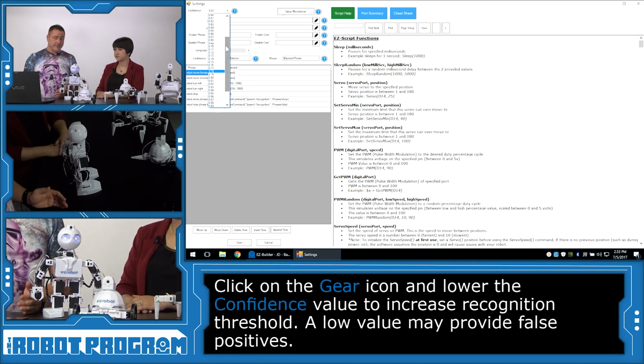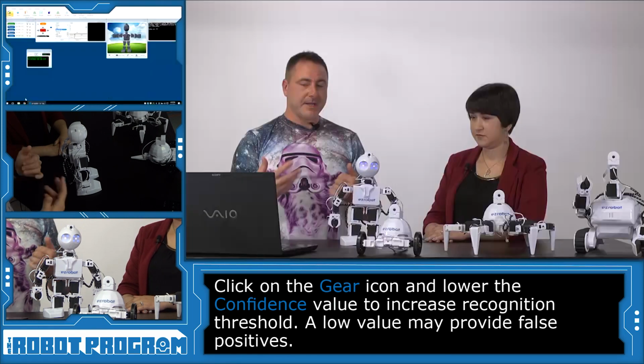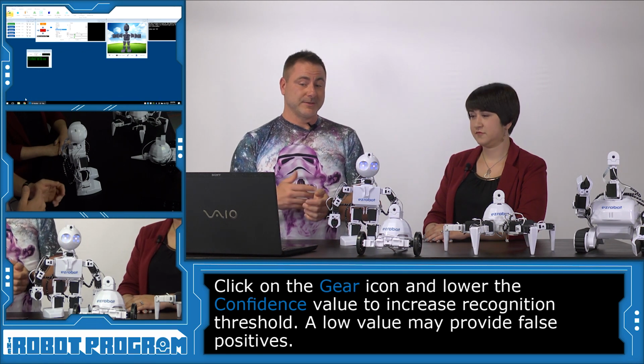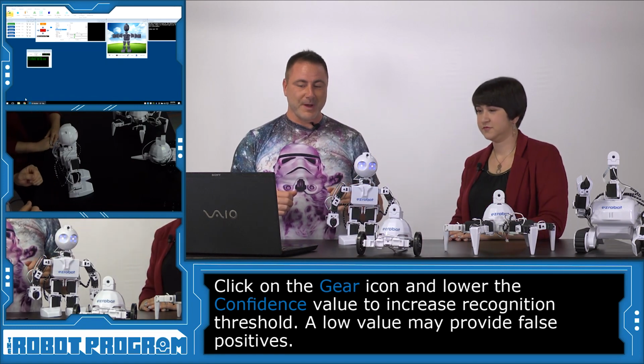That means we're probably going to want to bring this down to around 0.60. Now, it will work, but if I'm just talking out loud like I'm talking right now, it may think I'm saying something and pick up some commands. So right now it seems to be doing pretty good. So let's try this again. Okay. Robot, move forward.